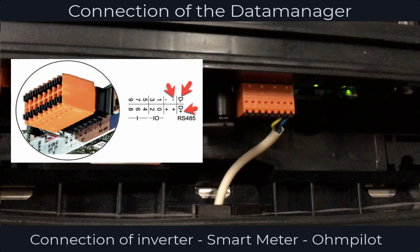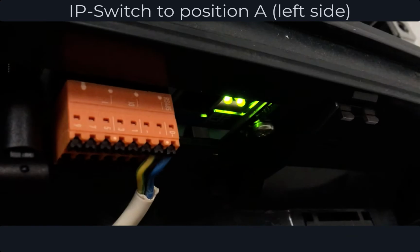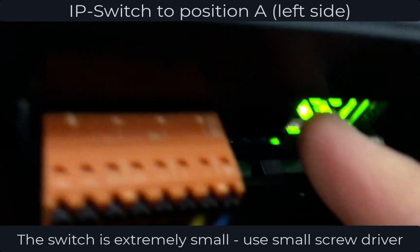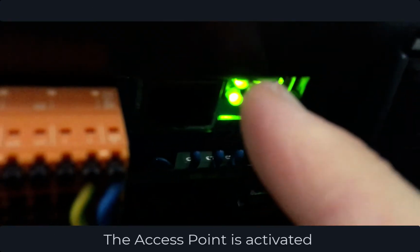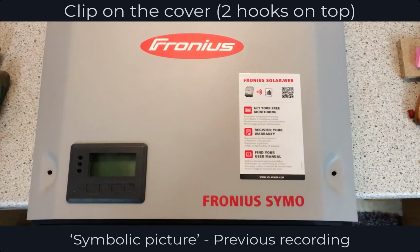Also, if there is no cable, you will still be seeing your solar energy production curve via the SolarWeb app. Bottom line, for those of you who have the cable, connect it back via the 3 pins. I'm using a standard cable. It works, but I recommend using shielded cables as we know them from network technology. Next, let's make sure the IP switch is in the position A, that is, left side. Position A enables the inverter's own Wi-Fi access point. The switch is tiny, best is to use a small screwdriver. Last but not least, let's mount the front cover again to complete the physical installation.